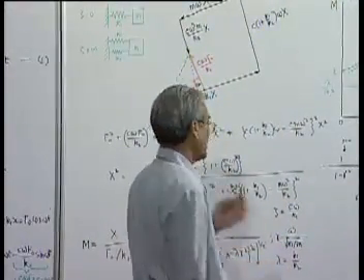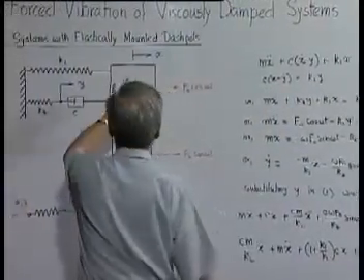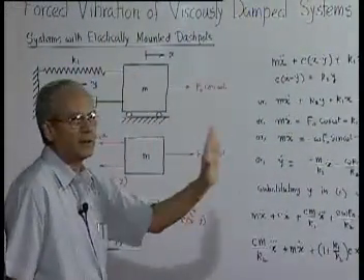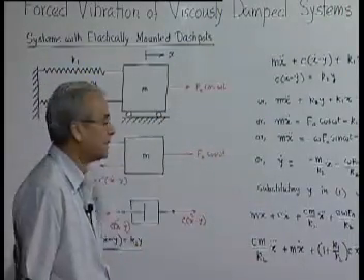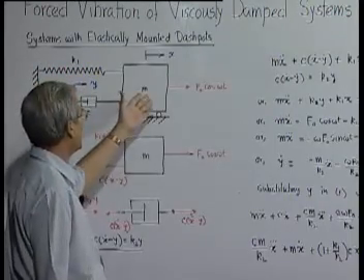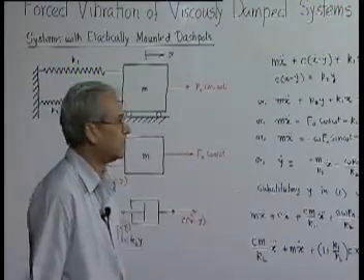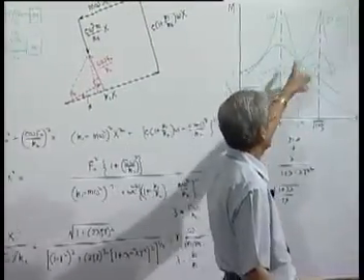So, this is another strategy which is a good example of design, that if you want to design something for which the frequency of excitation is continuously varying over a wide range, then we can always design it in a manner so that its maximum deflection will be minimum in the whole range if we design it in this fashion.